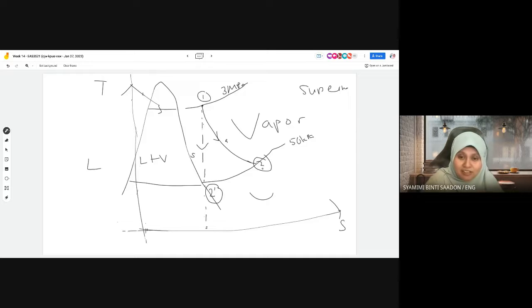So this part is totally vapor. Because when it enters the turbine, exiting the combustion chamber or boiler evaporator, it was at higher temperature and pressure. So it is quite impossible to consider that the fluid at the inlet of the turbine is still in the liquid vapor phase, because before the turbine we have the evaporator or boiler, right?